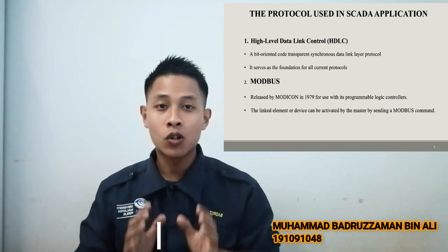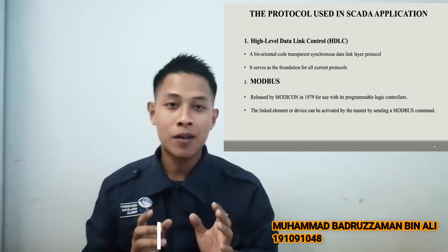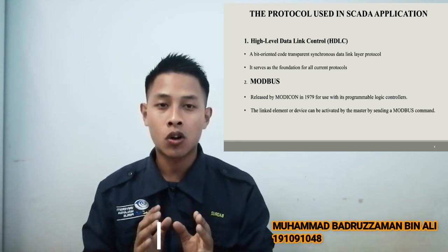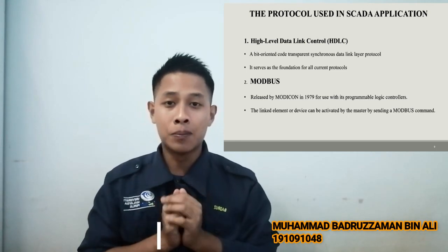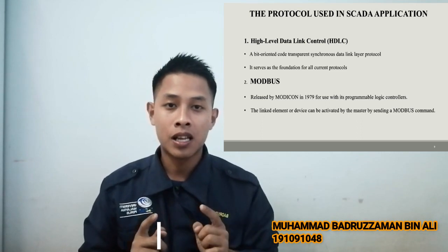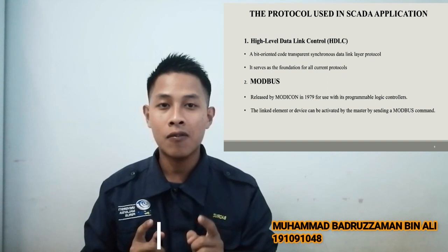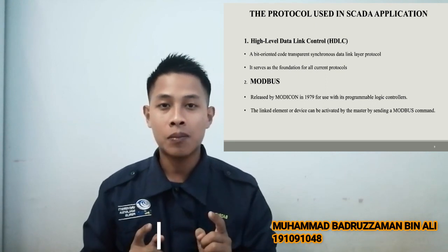Next part, the protocols used in SCADA applications. High-level data link control, HDLC, and Modbus are the two most extensively utilized protocols for SCADA applications. High-level data link control is a bit-oriented, transparent, synchronized data link layer protocol created by ISO.